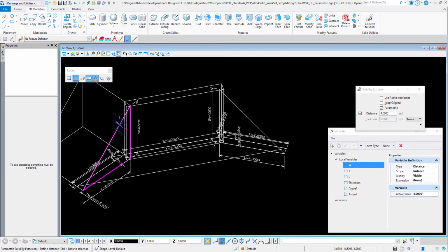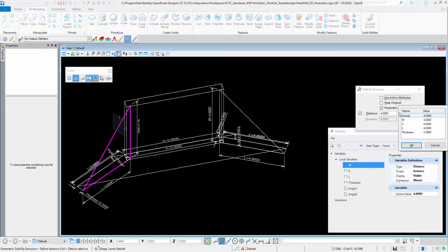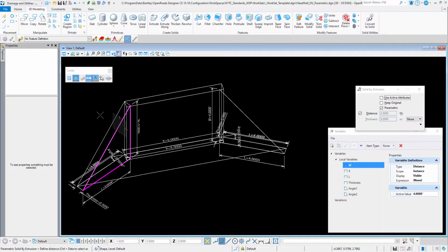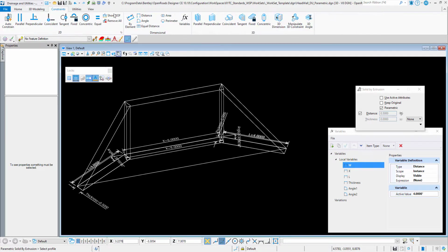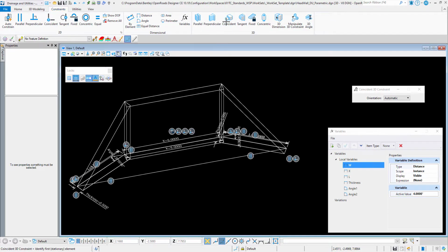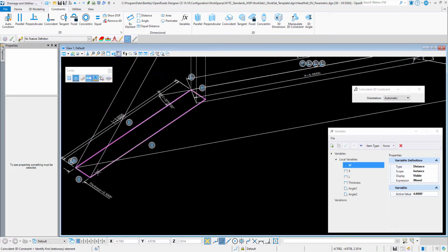And then I'm going to extrude them. Now, because my angles are on the top plane or on the flat plane, and these triangles are perpendicular to it, instead of assigning them angles, what I'm doing is just fixing them to the box that I had drawn underneath it.